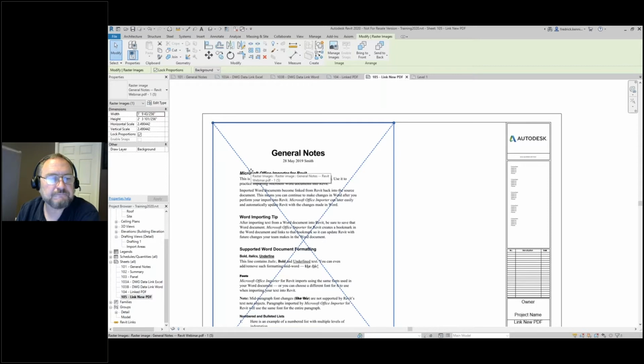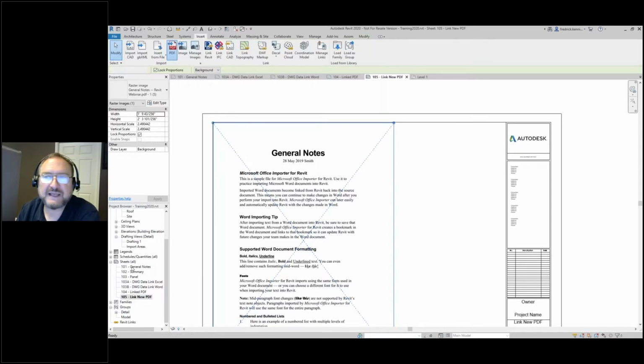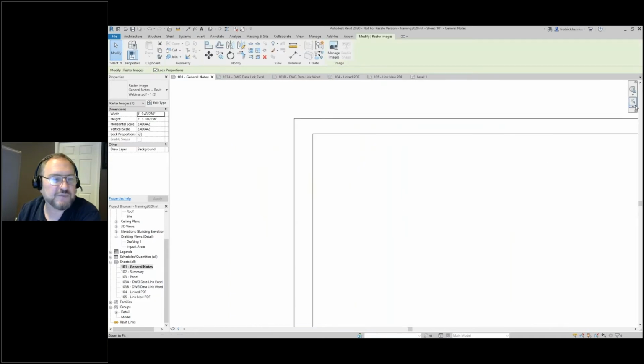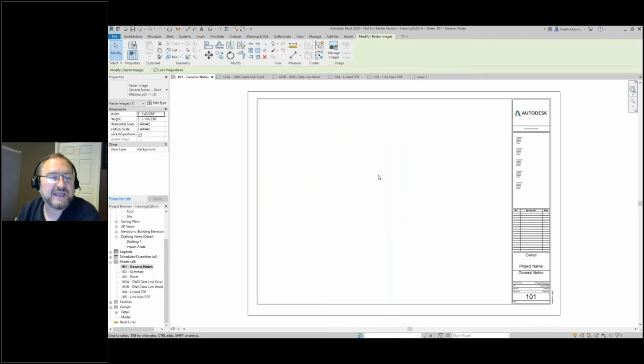And now I'm going to shift gears, and I'm going to go to my general notes sheet again. And I'm going to show you another faster, more pristine, perfect, easy way to get Word and Excel data into your Revit project with very exact formatting. When you install the program, which here in the upper left on this Axiom ribbon panel, you'll see is named Microsoft Office Importer. These buttons that I'm putting my cursor over are the program.